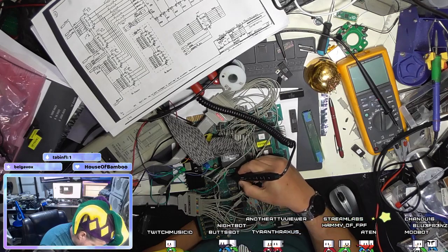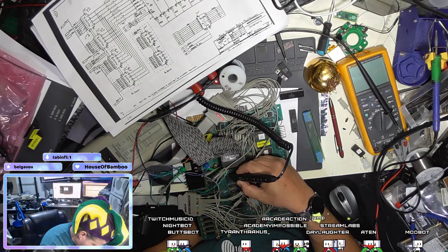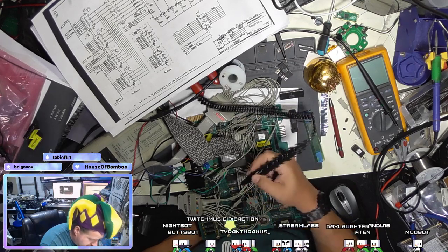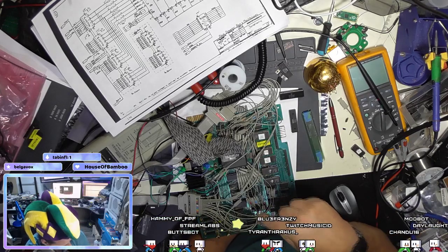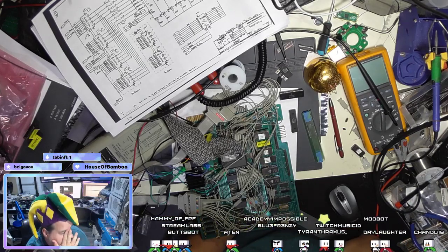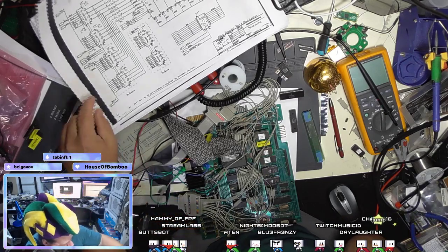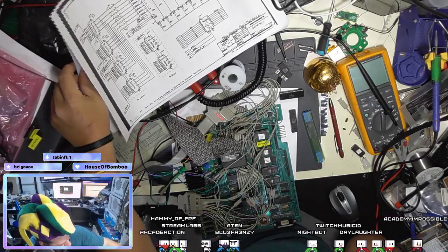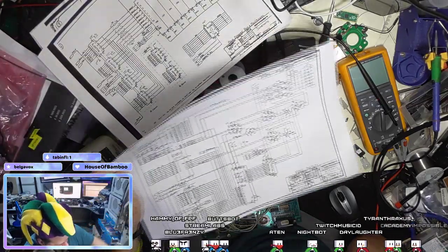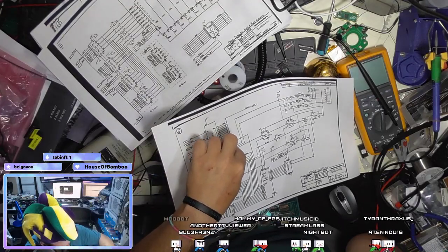The reason why I say it's not initializing the video is I get nothing coming out of the horizontal sync, vertical sync signals coming out of the 6545 processor, the video processor, the CRTC, this chip here. Nothing comes out of H-Sync or V-Sync.